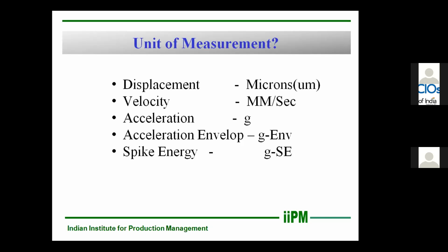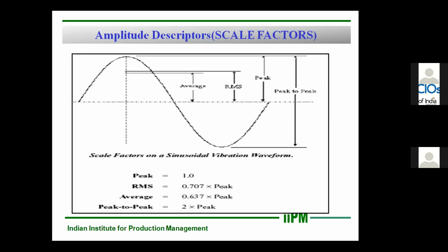So we can use a vibration analyzer, or you can use ultrasound instruments available in the market, because ultrasound instruments will also help identify whether I am providing an adequate amount of lubrication or not, and the early stage of bearing defects can be found through ultrasound.